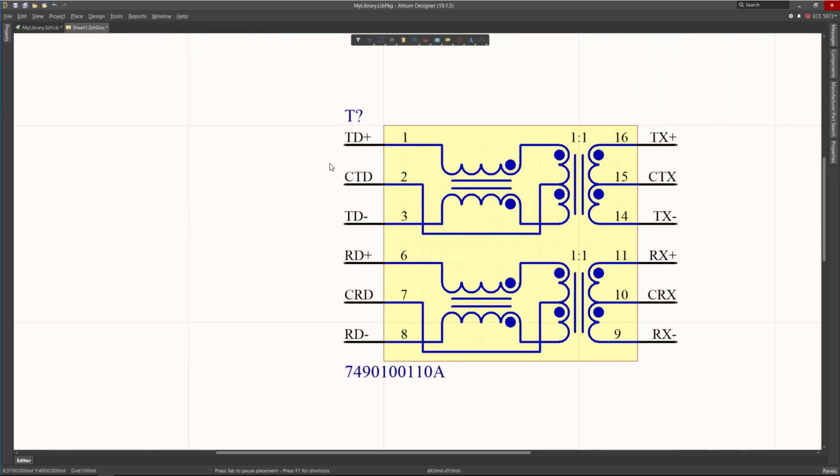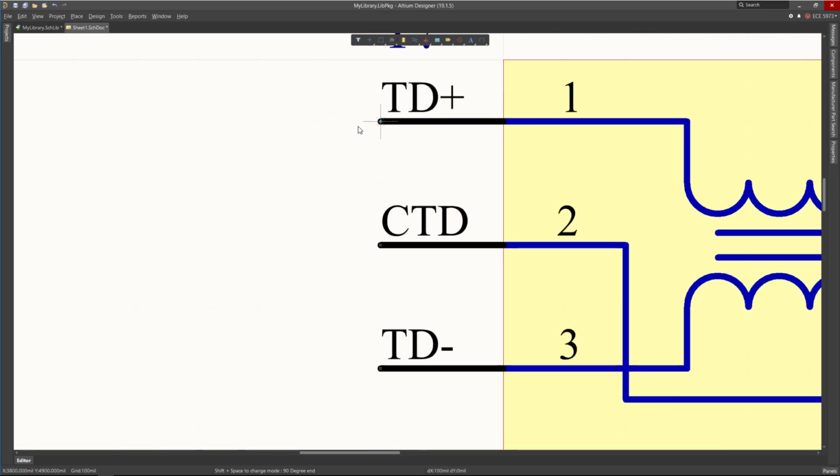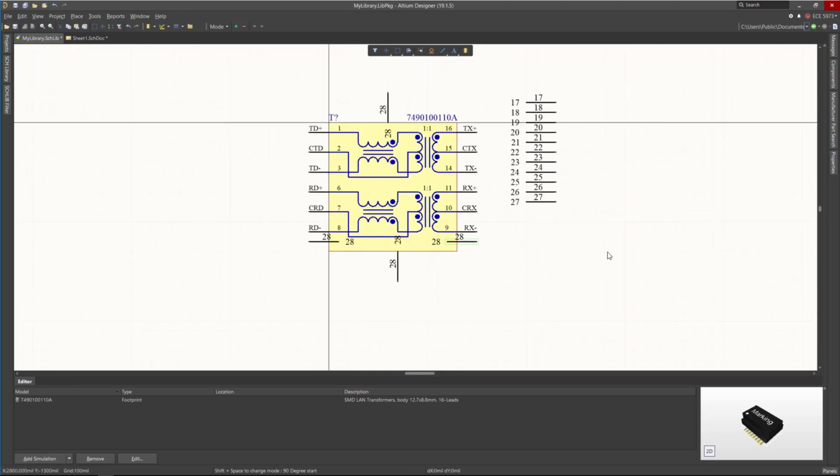Now when I go to the schematic and I would connect, control start connection, and let's say you see how the cursor is changing to red and snapping into that pin because it's in here. So if you move here or here, you don't see this red cross in here because this is not electrical properties or not the hot end. So if you start in here, you come closer, so it snaps automatically. You see, I'm 100 mil distance, it snaps automatically to the electrical connection of the pin. So now it's connected. You can tell that it's connected. Okay, let's go back.